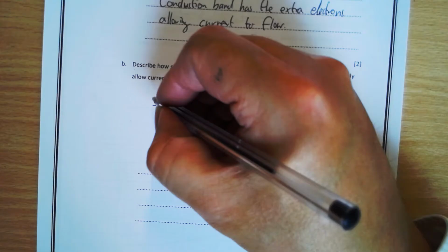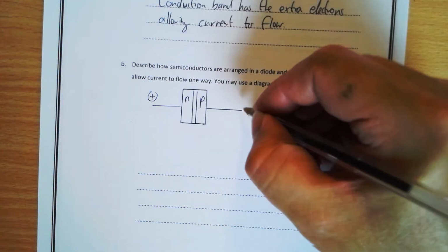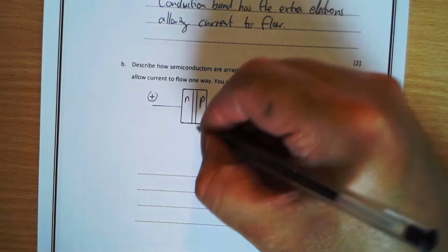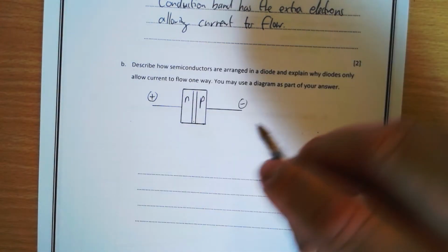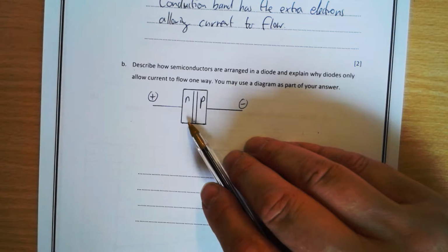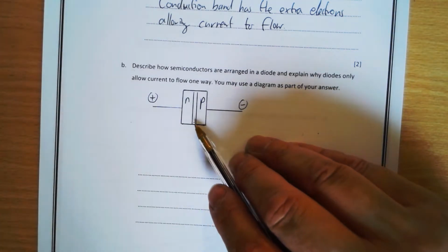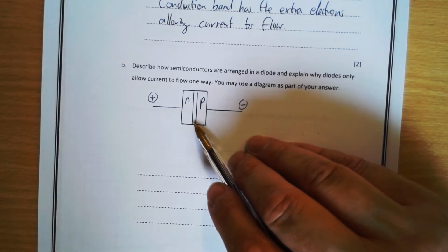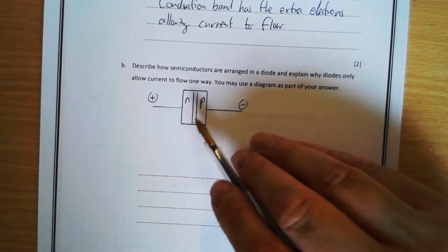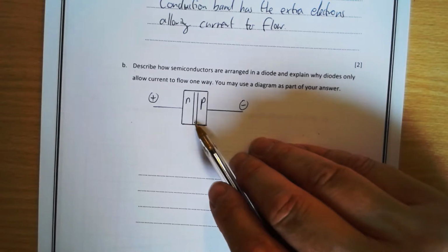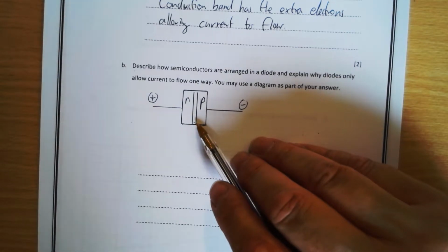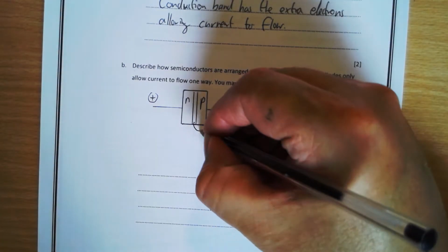If you connect it on reverse bias, positive and negative, basically what happens is that the electrons from the N-type go into the holes created by the P-type, so you end up with an area here with just neutral, which acts like a neutral semiconductor, and doesn't allow any charges to flow, so no current can flow, and we call that a depletion zone.